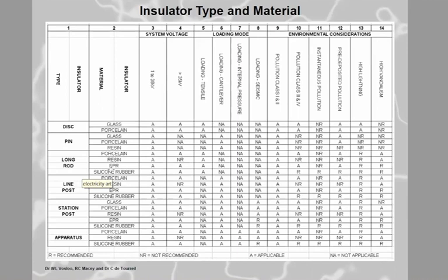And as the material cracks open, what happens now to the pollution? It moves into the crack. Right, so with EPDM, the surface cracks open, what happens to the pollution? Into the cracks. What happens to the area? Ta-da, goes big. What happens to R? Down. What happens to I? Up. See, rho L over A.